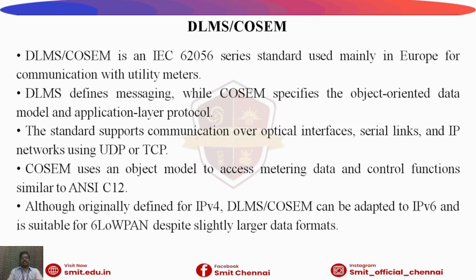Next one is DLMS/COSEM. DLMS/COSEM is an IEC standard used mainly in Europe for utility metering. DLMS defines messaging while COSEM defines the object-oriented data model. It supports UDP and TCP over IP networks. The protocol can be adapted to IPv6. It is suitable for 6LoWPAN despite slightly larger data formats.